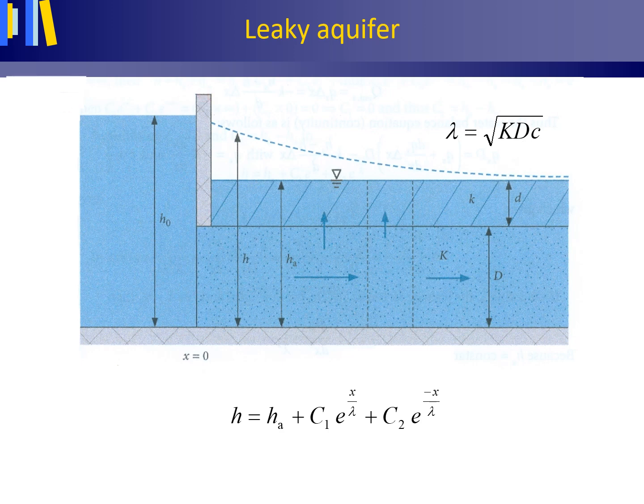Water from the river flows horizontally into the aquifer, and part of the water seeps upward through the confining layer, where again, to keep our feet dry, it is pumped off into the river again. Because of this, both the volume flux through the aquifer and the hydraulic head in the aquifer diminish from left to right.